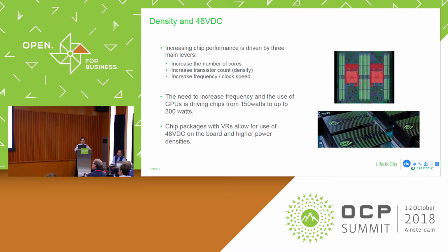At the same time, one benefit of 48-volt is that it can gain higher densities. I'm not going to go further here, as there are other reasons to consider that are not in this topic, for example the bus bars. If you're using 48-volt bus bars, the bus bar carries the same current but you get more power there. But 48-volt is more about gaining higher density racks.